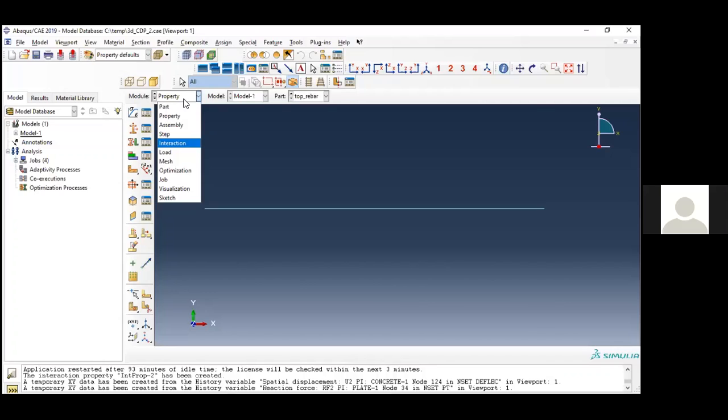So what will be the difference in smeared modeling? Is it only in the input parameters? Smeared modeling, as I said, if you are using it for monotonic loading, you can use the smeared crack model. I think in results you won't have much difference, provided that the input parameters you use for both models are the same. But the input parameters you give are defined differently.